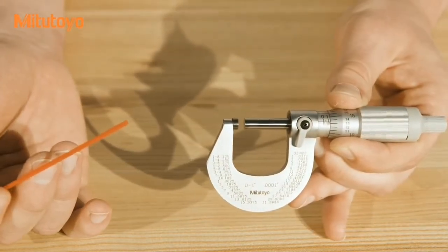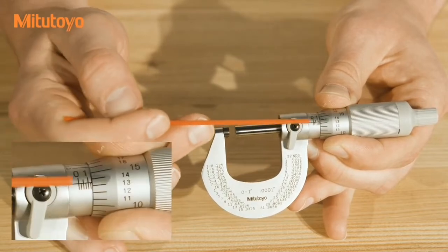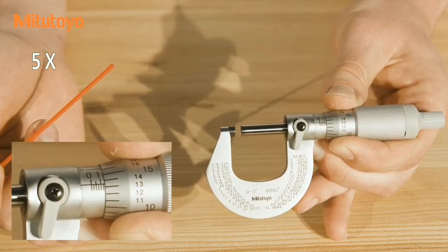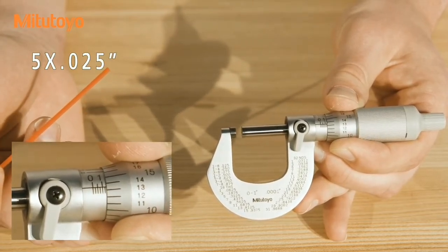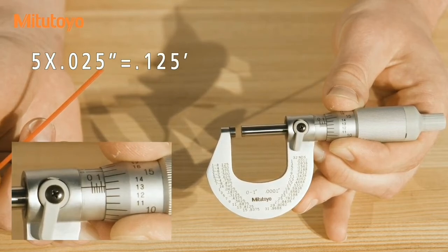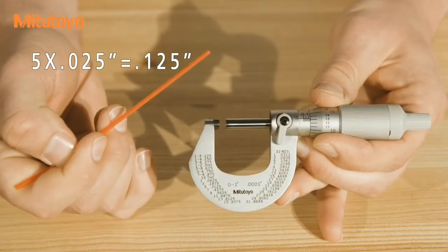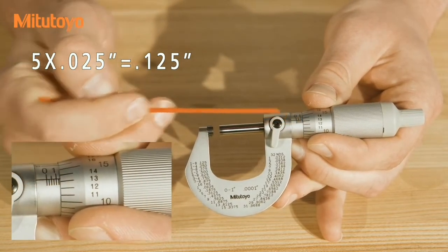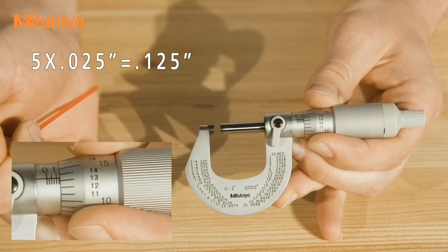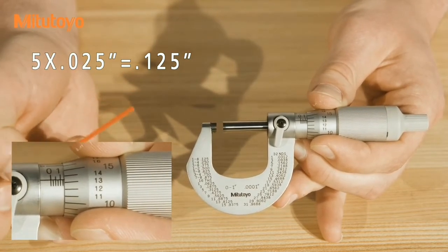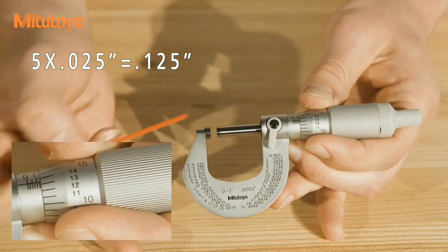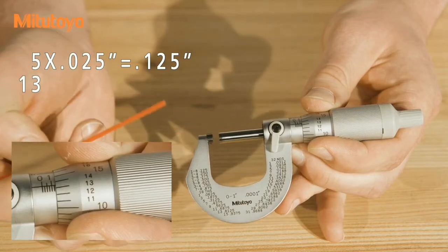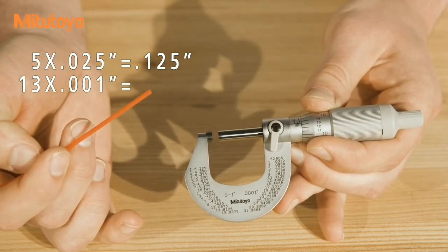In this micrometer that we have locked a reading into, the last line which is fully visible is the 5th hash mark on the main scale. So the reading for that would be 5 times the graduation of the main scale, which is 0.025 inches, for a reading of 0.125 inches. The second set of graduations is read by finding the line which is nearest but not past the line running down the sleeve. An easy way to make this determination is, if the horizontal line is between two thimble graduations, use the smaller number. In this case, the line is between 13 and 14, so we'll use 13. And on this micrometer, that's 0.013 inches or 13 thousandths.